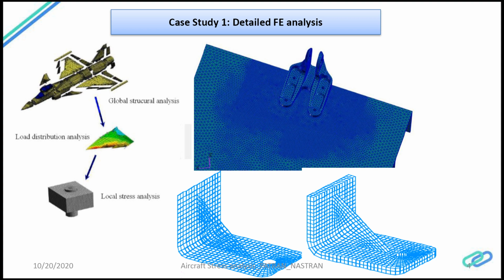What is your understanding of composites? Though composites are not covered in this course, I'm just giving you a typical scenario of how they will ask you about composites: what are anisotropic properties, how you can idealize the composite within the finite element, what is the PCOMP card in Nastran for composites, what parameters you need to specify, what output you will look at, and what stress you will take for core.